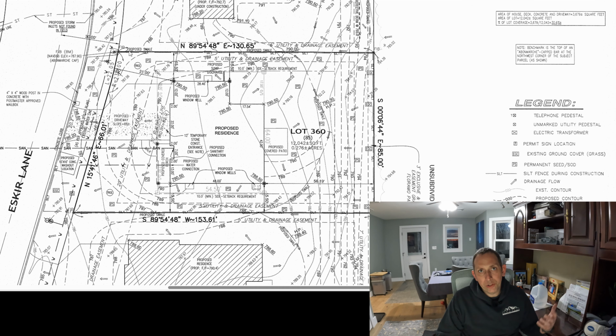You always want drainage away from the house. So now, as we've discussed, the back of the lot's higher, so it's going to kick water at the house. So we have to put a small swale in, which you'll see here, that is going to split in the middle, and it's going to shove all this water.